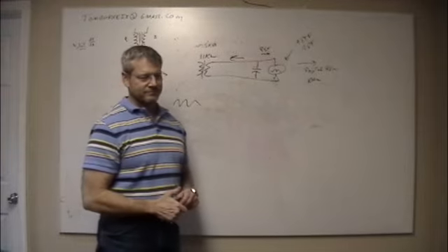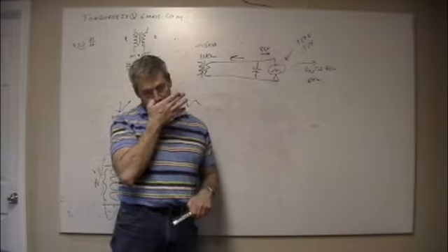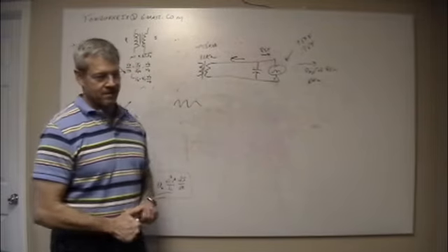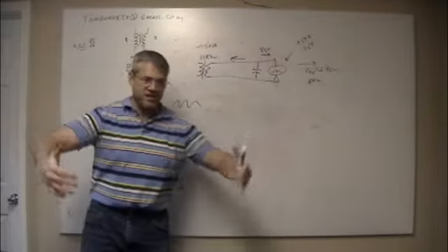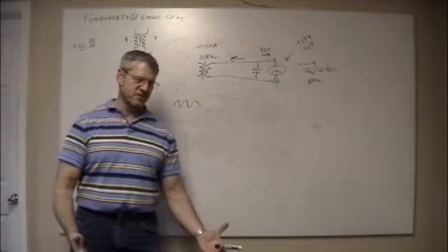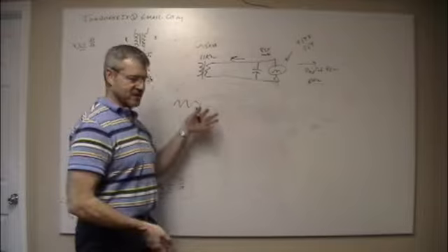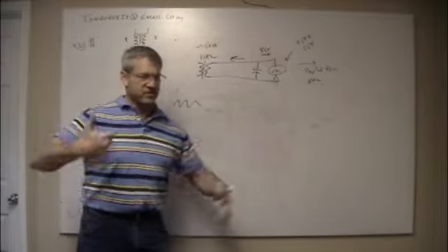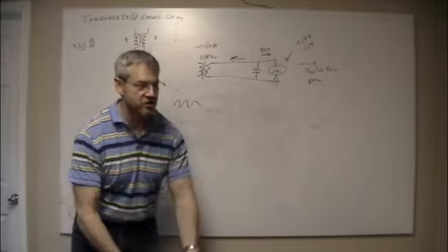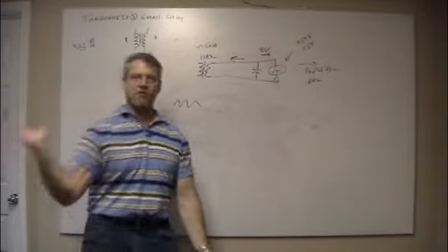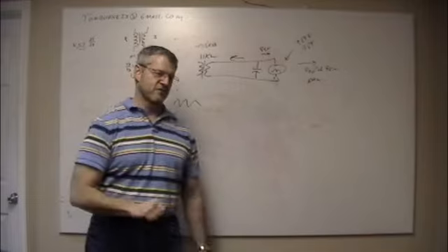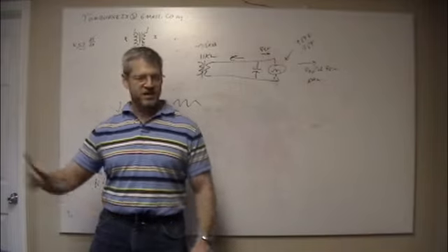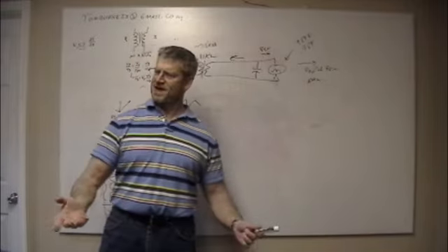And I guess capacitors at that kind of size are highly expensive. Yeah. And a big AC motor's less expensive. It used to be. I don't know about now. Yeah, it's less expensive than one of those things. So if you've got these motors sitting here running, you're using more energy overall. But because your power factor comes back closer to 1, you're getting charged less overall. So you're wasting energy to get a better power bill. That seems backwards, right?